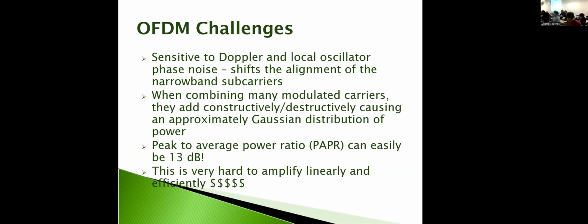That's an approximation, but 13 dB is 20 times, right? 10 dB plus 3 dB: a factor of 10 and then double it from that 3 dB. So it's 20 times the baseline.